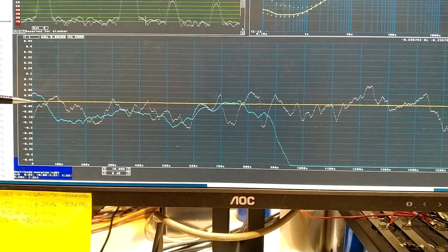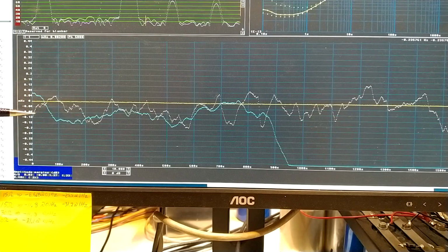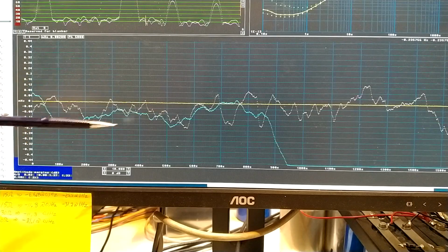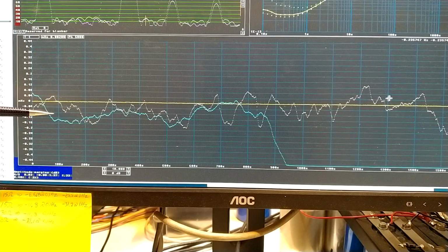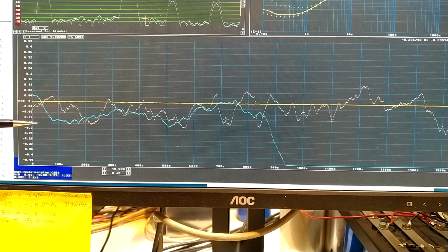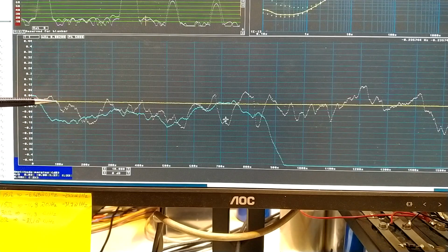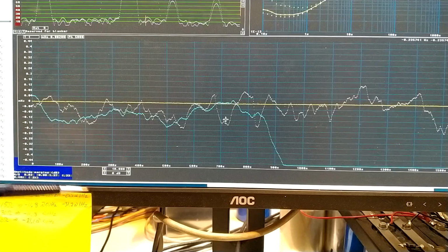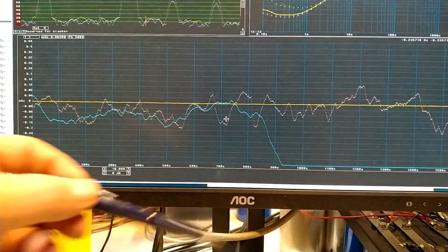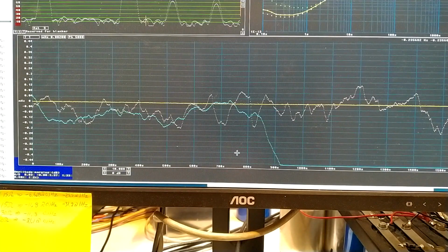The blue trace is the phase angle that I measure between input and output. And it doesn't correlate to the frequency. So it is caused by something else, and that is of course causing phase noise. The time scale is 100 seconds per division, from here to here. And then suddenly something dramatic happens here. That's when I entered the room for a short time and then went away again.